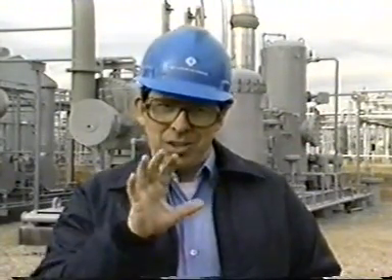Minimum inlet gas temperature is set by the viscosity of the glycol being used. Depending on the composition and pressure of the gas, hydrates may form at temperatures well above 50 degrees Fahrenheit. Therefore, a higher inlet gas temperature is required to avoid plugging problems from hydrates. Now, low inlet gas temperatures increase the tendency of glycol foaming. As you will see later, foaming creates significant operating problems. Now, in the normal operating range of a glycol dehydration unit, inlet gas pressure is not a critical factor.